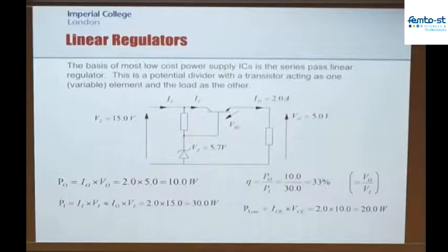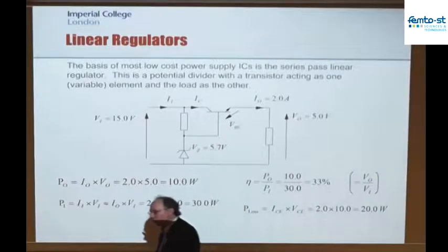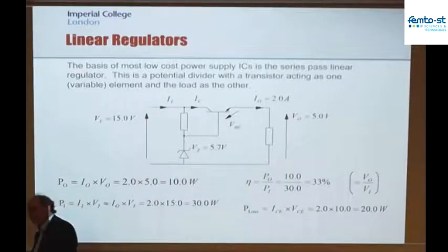If you think then about the specific requirements for an energy harvesting device, actually the thermal management problems may not be significant at all because the power levels are so small. So if I've got 10 microwatts and I'm wasting 5, well, 5 microwatts is not really going to heat anything up. So it's not really a thermal thing. It's not really a problem in terms of wasting battery power from an energy harvester because the whole point was to get rid of batteries in the first place.